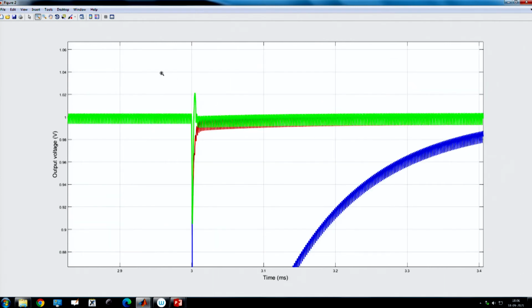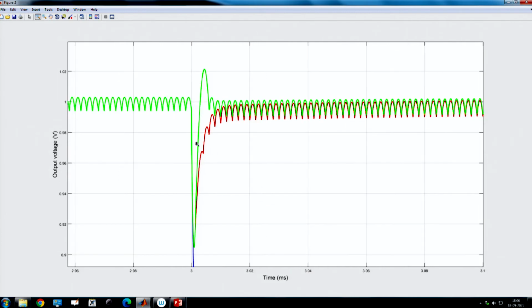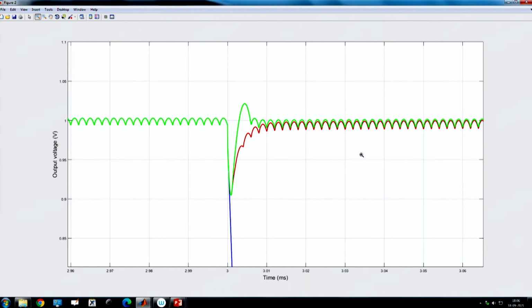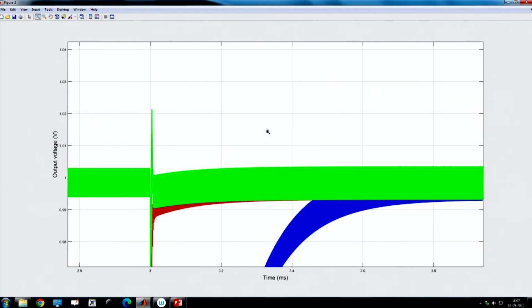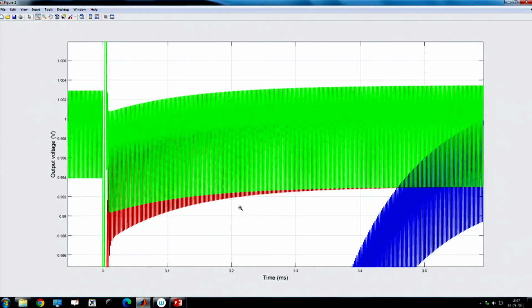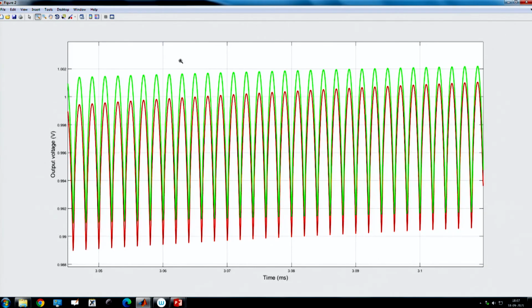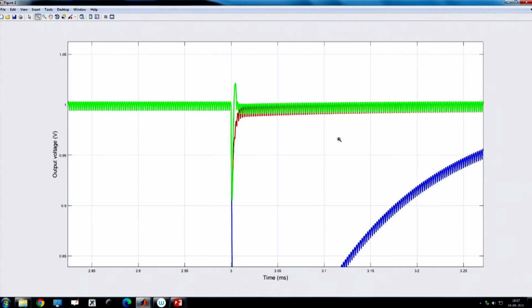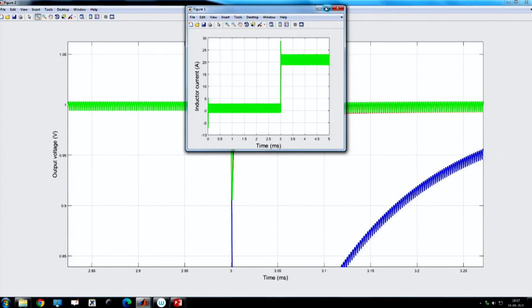when we consider our tuning, large signal tuning, it is recovering in almost 3 cycles, whereas load feed forward is taking some more time using the regular current mode control with load feed forward, and it is somewhat sluggish response. So, it takes a few more cycles to reach steady state, okay. But it is good that both are giving fine results with load feed forward, but optimal gain makes it even faster, right. So, you can just check it here.